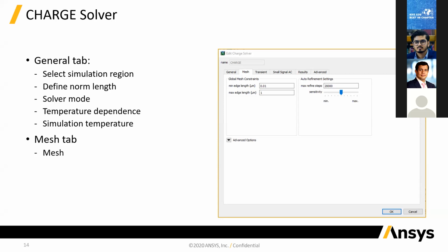And so as it breaks down the mesh and makes the elements, triangular elements, smaller and smaller, you can set a limit as to how small you want it to be. And this is where you define it. This parameter is usually more important, where by this you can control what would be the finest mesh that you get in your simulation volume.